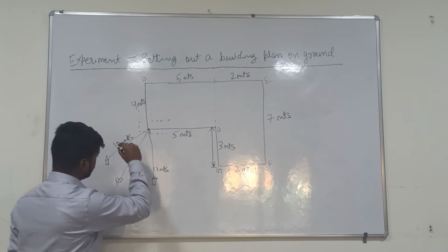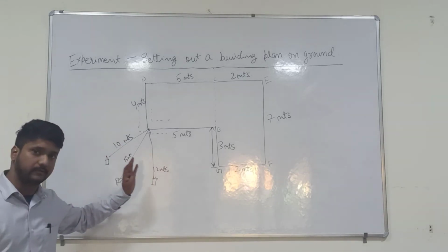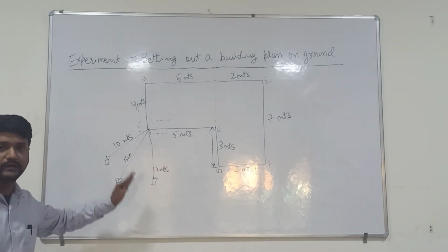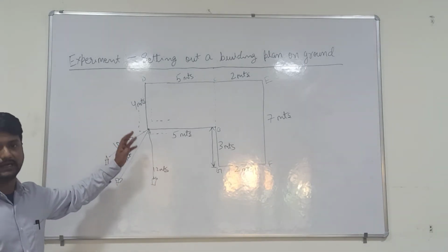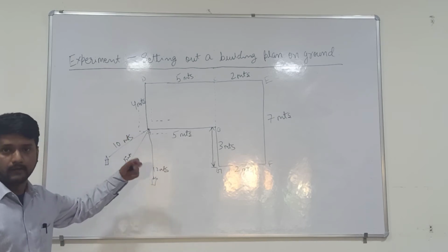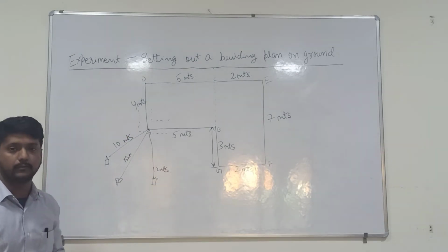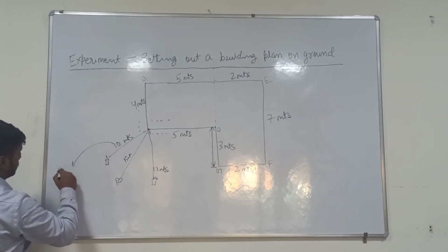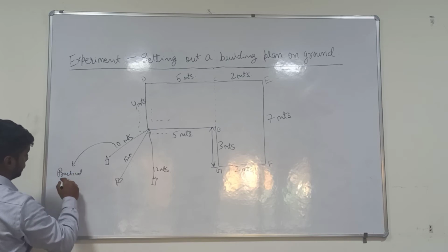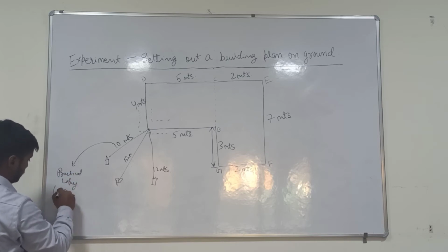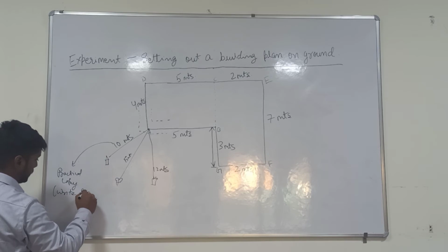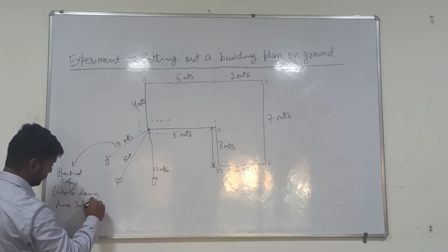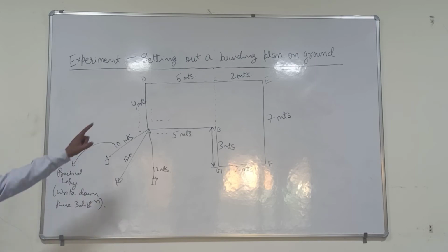I am just taking an example. If you know these 3 distances from 3 different permanent points, you can start your work from the exact same point A if you wish to. Whatever practical copy you have, you have to jot down and write these 3 distances. So that is the first step that you have to follow in order to establish the station.